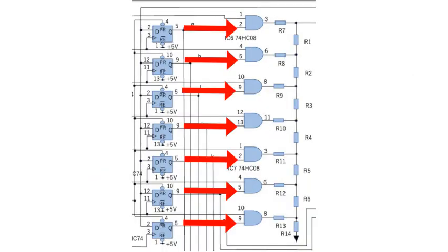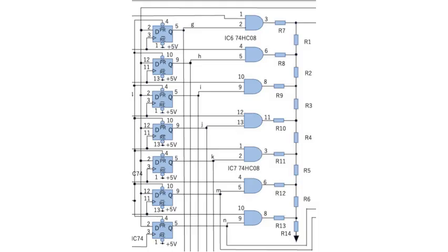Each output of the flip-flops connects to the inputs of the AND gates. Other than the first AND gate, whose input is permanently tied to 5 volts, each AND gate outputs a low initially, as each output from IC1 starts low. This leaves the MSB as the first approximation, shifting down after each clock tick to perform the analog to digital conversion. For example, let's say we have an analog input voltage of 4.2 volts.